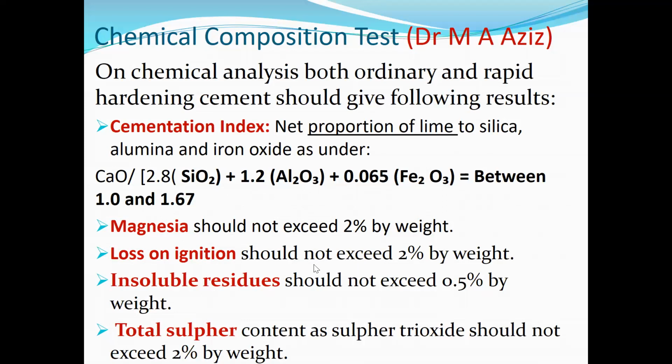Insoluble residue, that part of cement that does not take part in chemical reaction, we called insoluble residue, and that should not exceed 0.5% by weight, and total sulfur content as sulfur dioxide should not exceed 2% by weight.